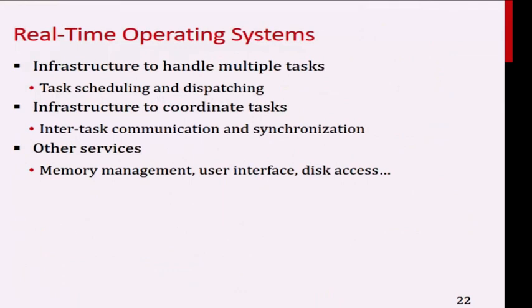And what is RTOS? RTOS is an inherent structure given to you to handle multiple tasks. The good part of RTOS in this module is we only need to understand the concept of how to use it. The actual internal behavior and how to modify it is at a higher level module. For this module, we are just understanding the concepts of RTOS and how we're going to apply it. It's quite easy because we treat all the details as a black box. I need to know the concept of how semaphore works, how mutex works, how message passing works, how queues work. I just understand the concept, and then I apply that concept in my design.